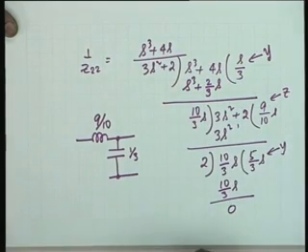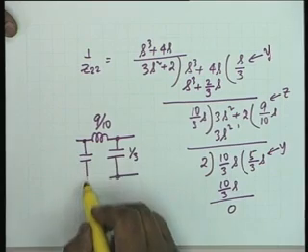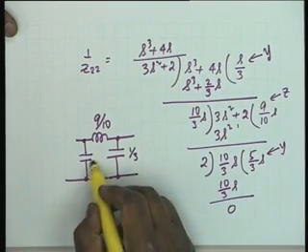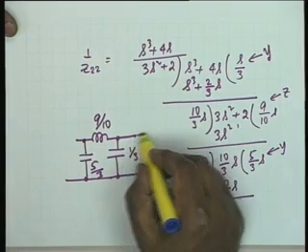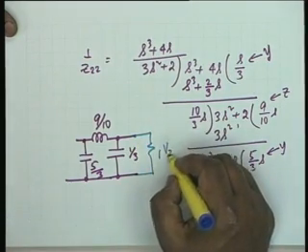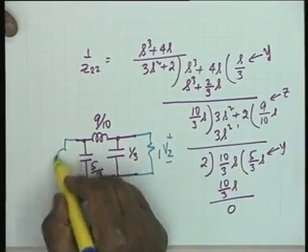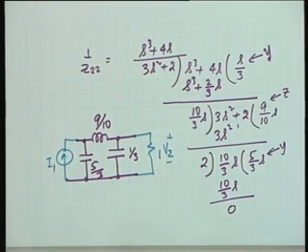It has to be, there is no other way, and therefore, the next capacitor is again 5 by 3 and the circuit is complete. All that we have to do now to complete this circuit is to add this 1 ohm resistance here. This is my V2 and the current generator here I1. This is the complete synthesis of the given specification.